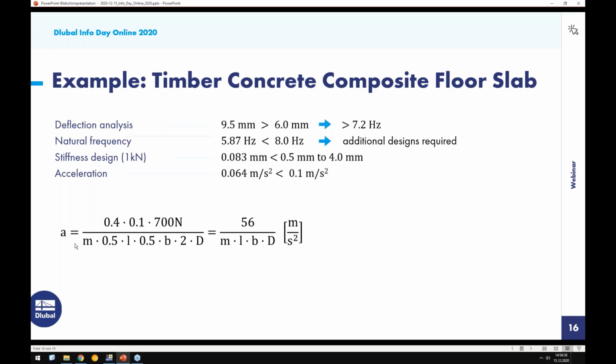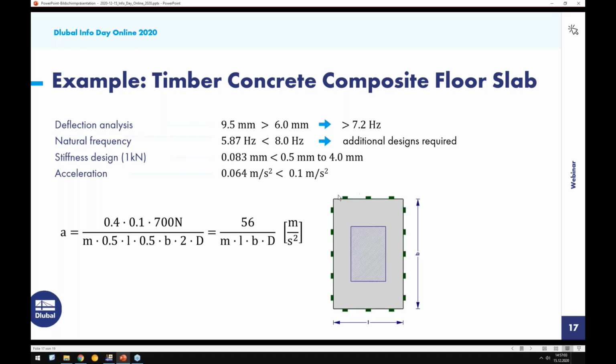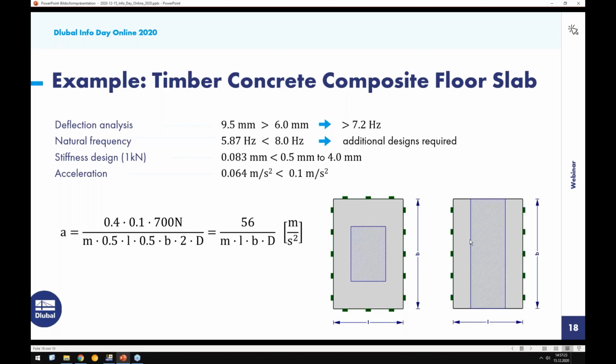When we think about this equation here on the bottom, what they have used in this example, they think about a 4-sided supported slab. As you see, they estimate only half of it goes into this support and into this support. So what we actually need for our example is this one, because we use it as a one-span beam. They have mixed it in this literature a bit. It was a bit confusing at first, but I figured this out at the end.